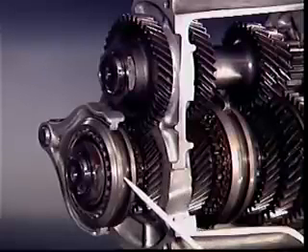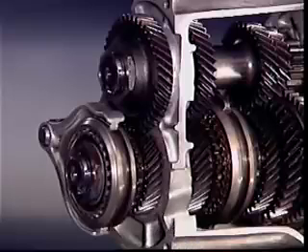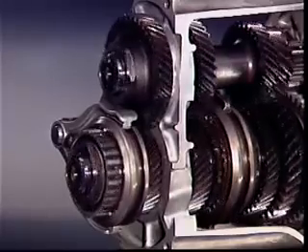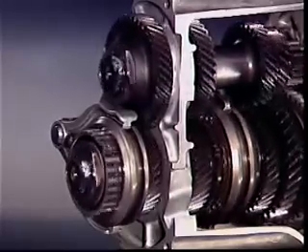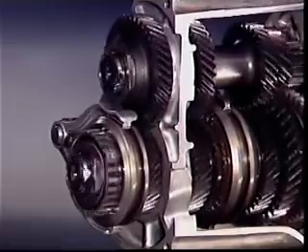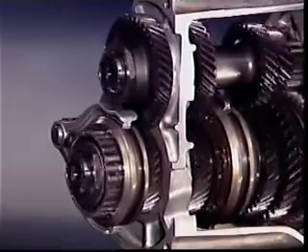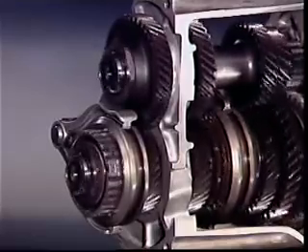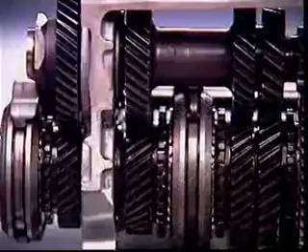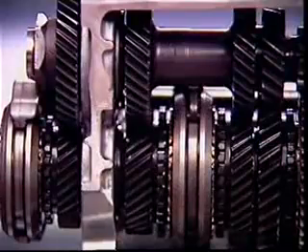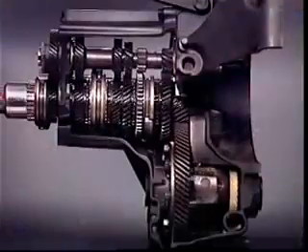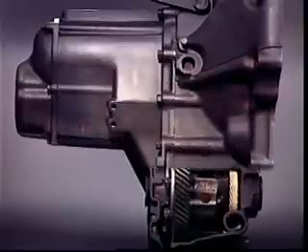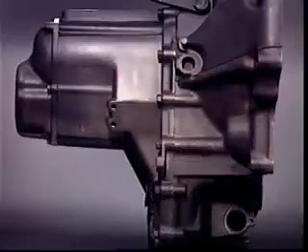The free gear has its own engagement sleeve and synchromesh unit beside it. Selecting 5th gear locks the gear to the shaft. The gear on the primary shaft is larger than the gear on the secondary, so an overdrive ratio is provided. The secondary shaft rotates faster than the primary. Gears constantly in mesh use helical gearing. Having the gearbox and final drive gears in one casing provides a compact and noise-free unit.